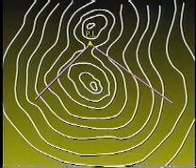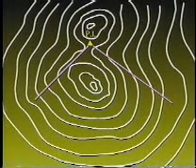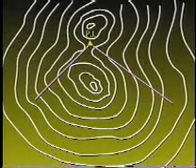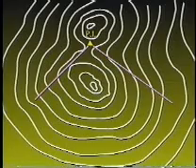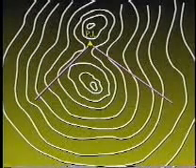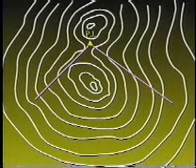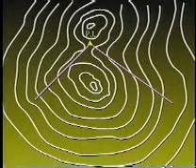Reconnaissance and initial studies for our highway project have identified the saddle shown here on our large-scale aerial mapping as a portion of the route. The first step in the design process is to construct a preliminary horizontal alignment. This is done by laying out tangents as shown here. Changes in direction of the route are designated as PIs, or points of intersection. Positioning of these preliminary tangents is determined by topography and the change in elevation between the various PIs.